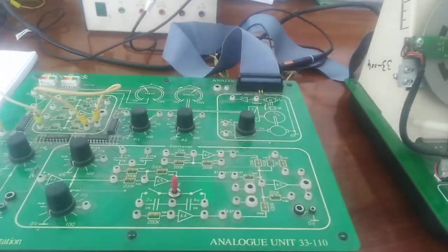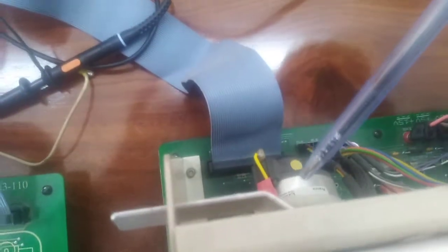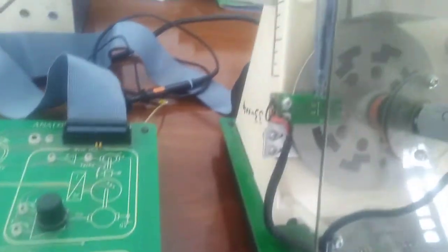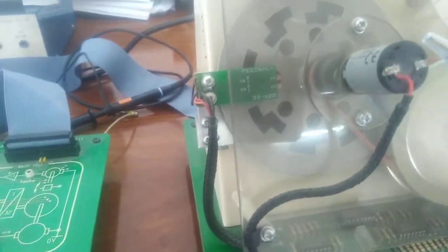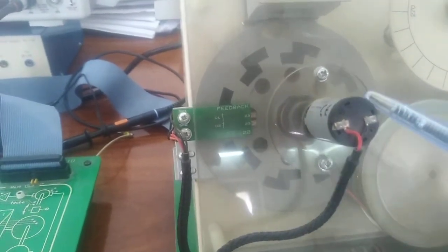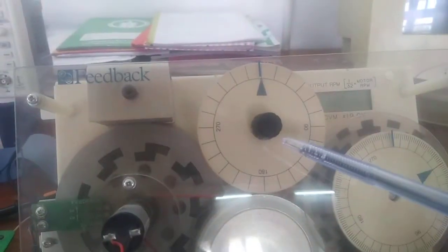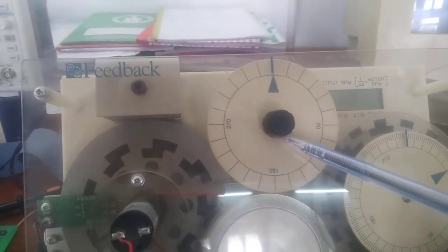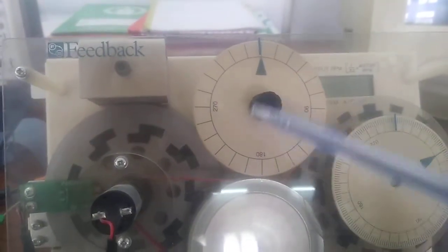So this is how it looks on the machine. This is the DC motor here, and at the shaft of the DC motor we are having this aluminum disc, which is the rotating disc, and further we are having the tachometer, which is a tacho generator, which gives the speed proportional to the speed of this DC motor. And this is the input rotary potentiometer. In this case we will not use it. We will apply a square wave in place of this input rotary potentiometer.